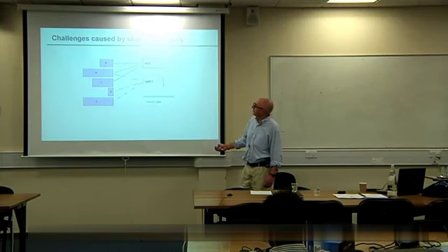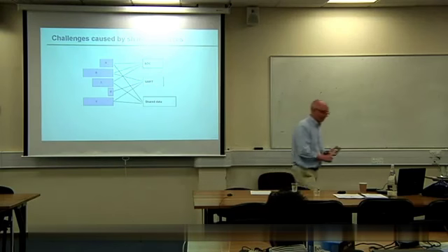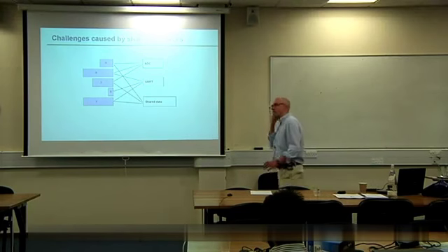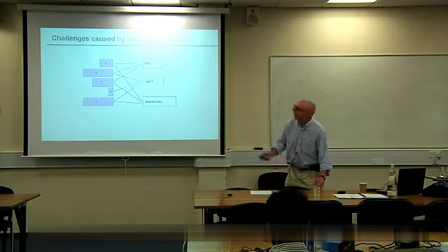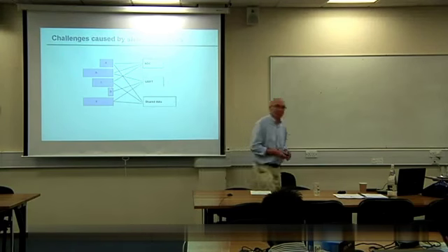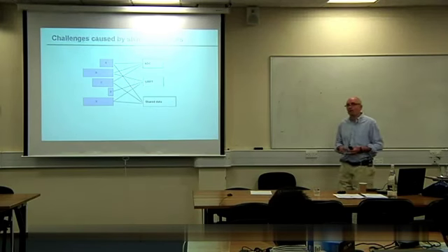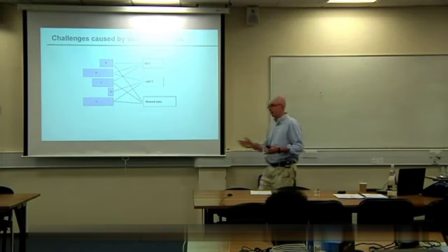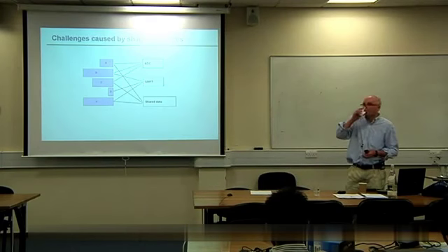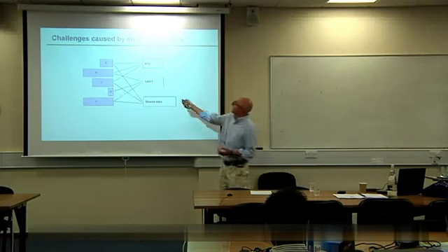Now, sometimes what people do in a system is, give me another potential solution that might avoid these conflicts between A, B, and C and the ADC. So we're having problems because these three tasks are sharing a resource. Give me one potential way of addressing that. Give them all their own resource. Okay, so we could have three ADCs.